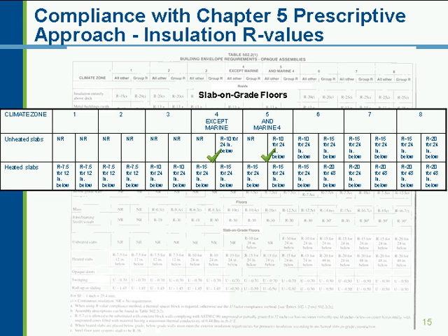If you have a heated slab, then this is going to be a slab with radiant coils in it or uninsulated ductwork running through the slab, you will always have to insulate the slab edge. And the requirements in that range anywhere from an R7.5 in climate zone 1 up to an R20 in climate zone 8. And then there'll be differences as far as the linear length of insulation for that slab edge too.